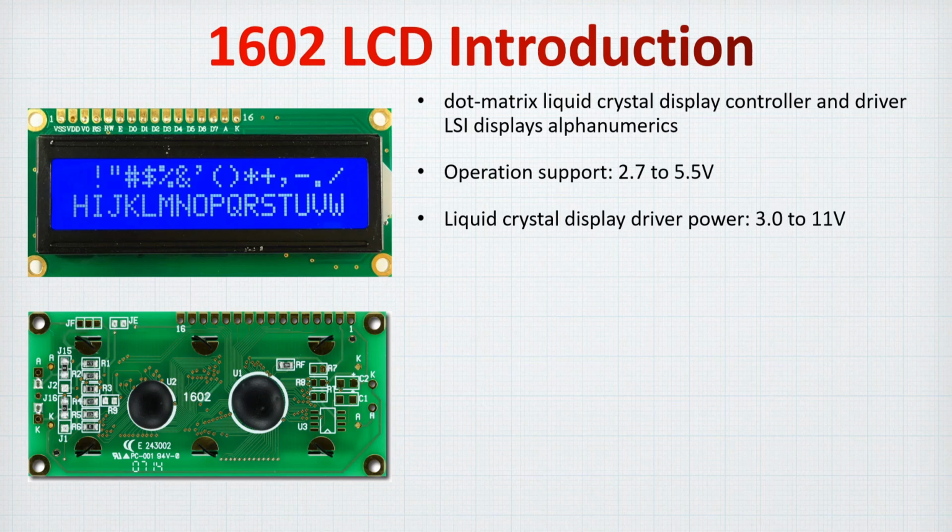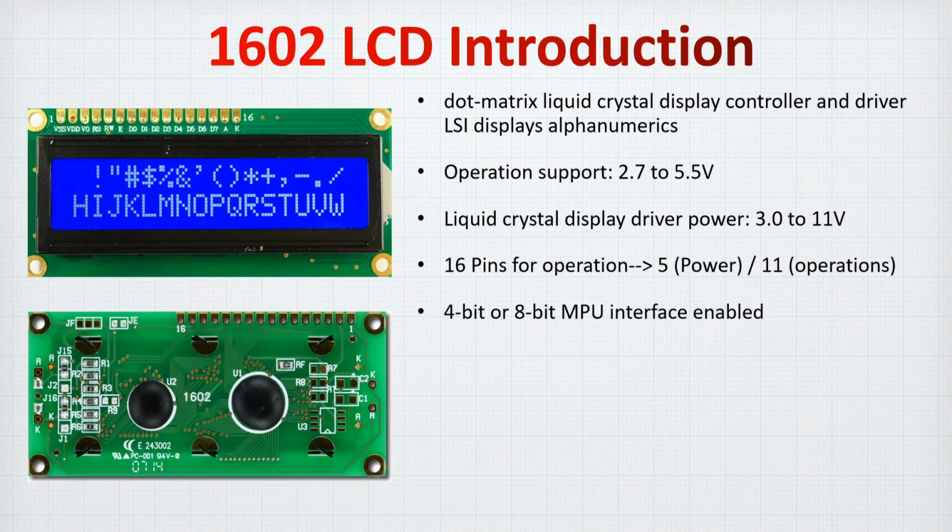Also the driver power can go up to 11 volts. I quite advise using 5 volts, which is quite standard for most LCDs. There are 16 pins for operation. There are 5 for power and 11 for operations.